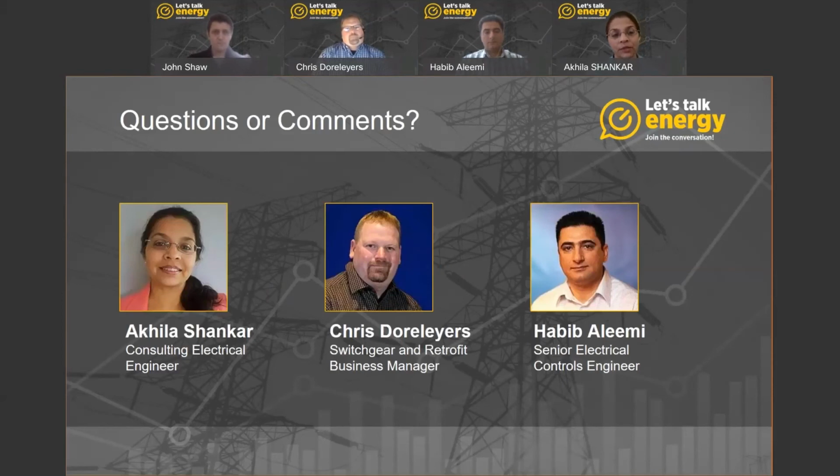Caterpillar has a lineup of standby natural gas gensets, which can start and be ready to accept load within 10 seconds. We are yet to design a project which brings in multiple gensets and parallels them under 10 seconds. But based on the controls that go on the natural gas genset, I believe it is feasible, but we are yet to prove it with a project.